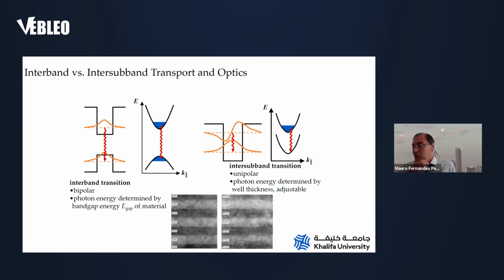What I'm going to show here today is something that is not based on optical transitions, but rather on electrons oscillating due to Bloch oscillations in the semiconductor, and that allows us to go to even lower frequencies, from gigahertz to terahertz. We will be looking into superlattices like gallium arsenide, aluminum gallium arsenide, and here you see a picture of the actual structures that we are going to investigate in this talk.